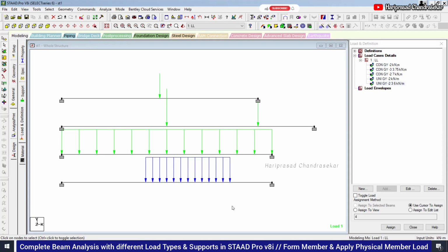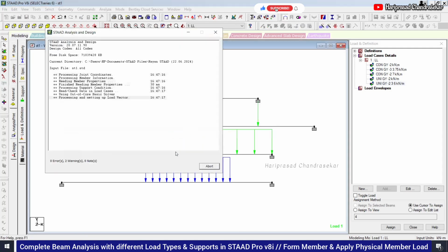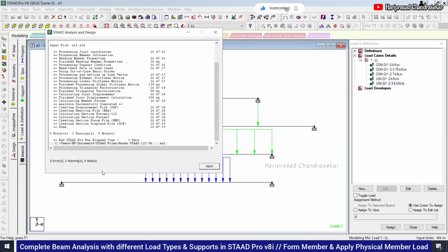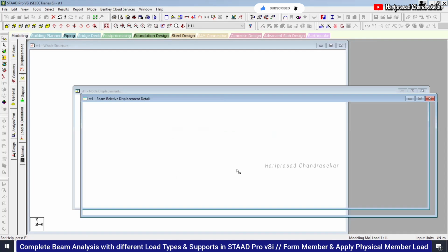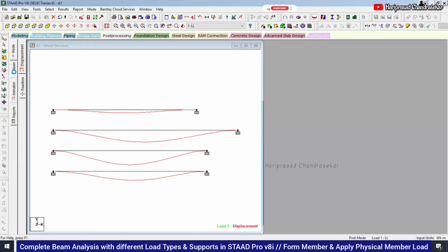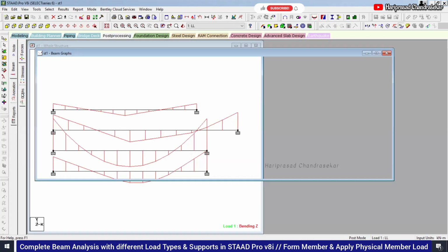Okay, actually in the book now they are considering it as a simple support. For that, we should not consider fixed actually. Okay, that is also there, but we consider everywhere fixed. But if you want to consider pinned, then I will tell you in the next exercise. Now it was correct. Now I will go for analyze. So no error means it's good, so that we can go for post processing. Otherwise, it will not. Now you can see the beam bending moment diagrams and all.